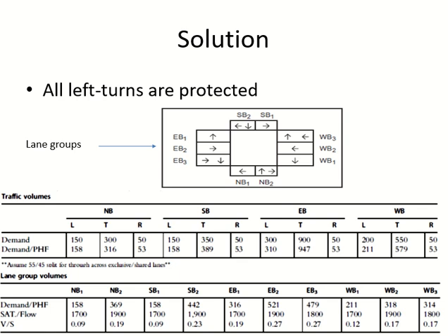These are the saturation flow rates for each lane group. In this question they are given. How to calculate it? You have to go back, like to high school or something, because we already covered it. Here they are given. So divide the flow rate by the saturation flow rate, and you will get a ratio which obviously would be less than 1.